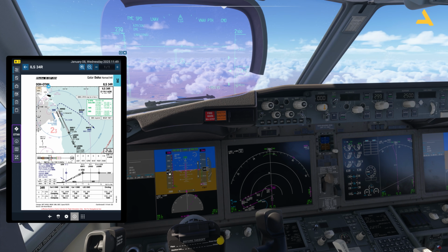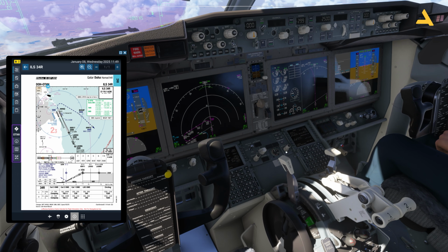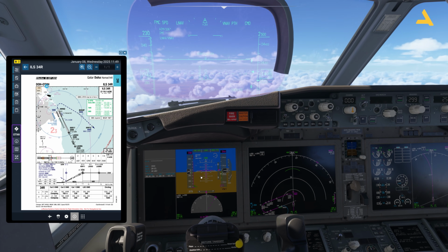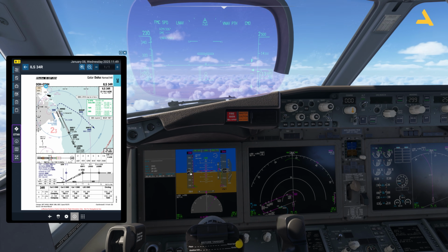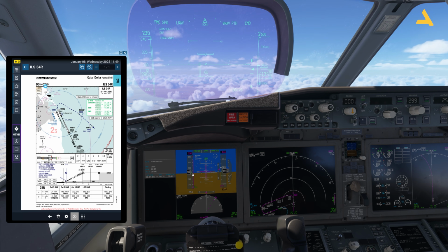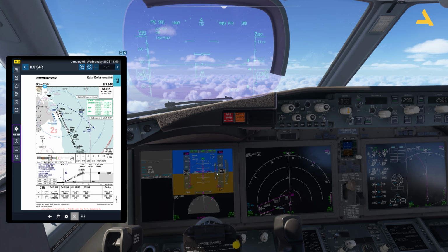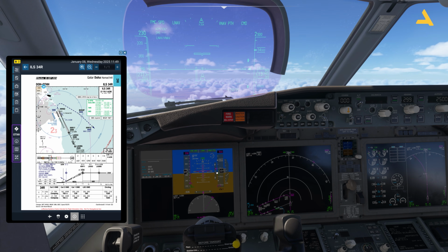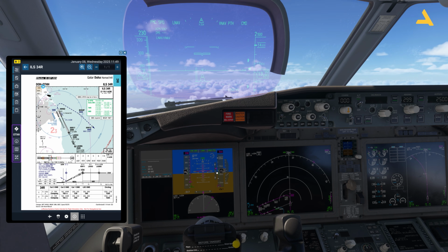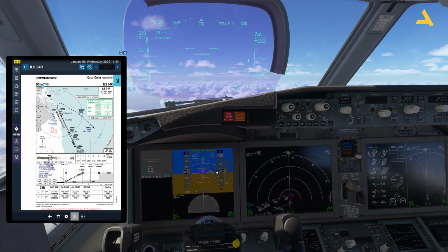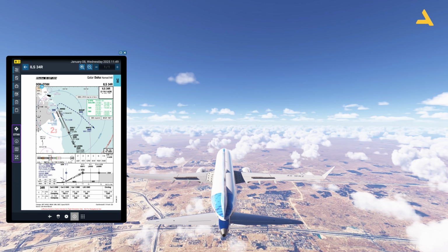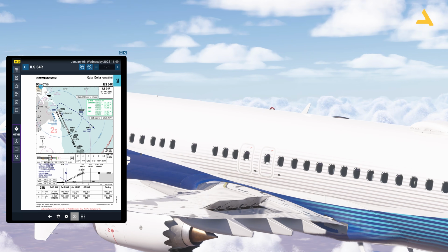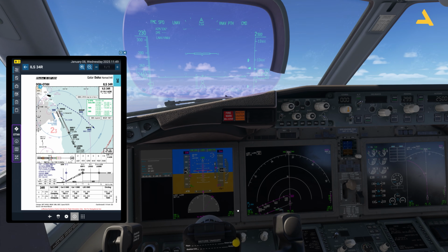this point. And now the speed is not reducing. So you can activate the speed brakes so that the plane follows this speed restriction without impacting the descent rate. You can see the plane is slightly lower than the descent profile, but it's okay. Now you can see the speed brakes are active. That's it.